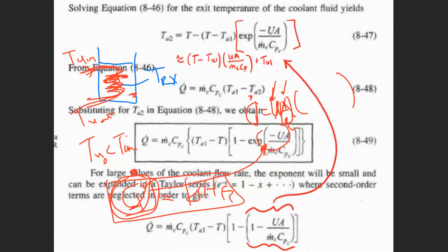And normally, when we've got countercurrent flow, you've got the log mean temperature difference equation, and this is where that comes from, that you want to calculate, not just use a single temperature, because the temperature of the utility is not really constant. This is warmer and this will be colder.